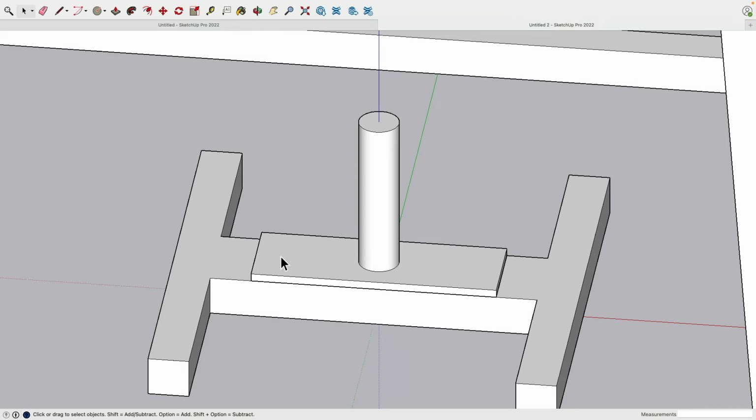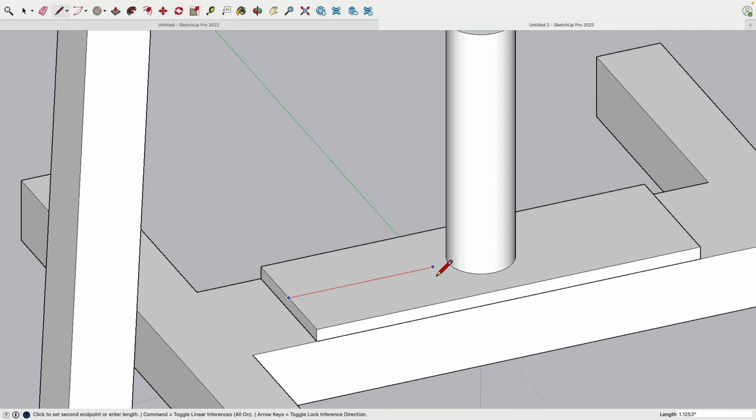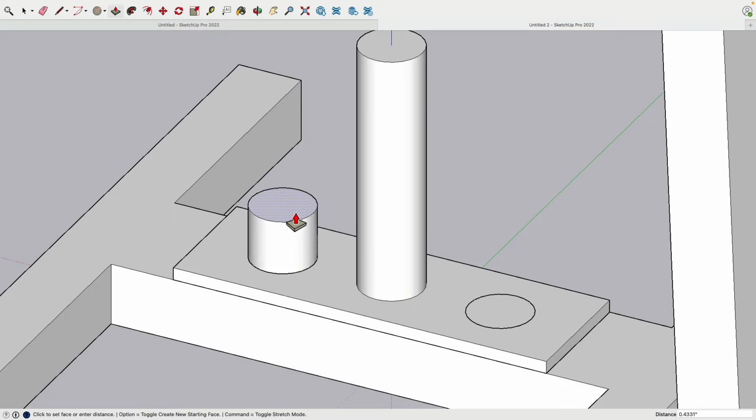I would like to have 1/2 inch diameter knobs left and right, kind of like for screw pieces. Here again, I can use the midpoint, draw along the x-axis till it touches there and here. So, circle, midpoint, 0.25. Same here, 0.25. And then clean up, clean up, clean up. And these we can move up 1/2 inch.